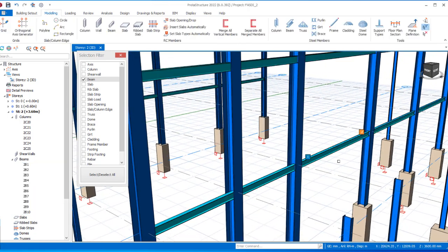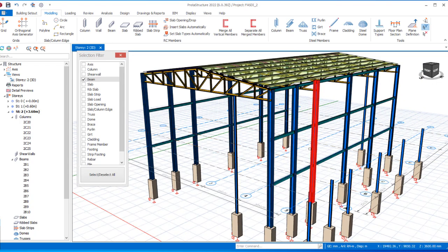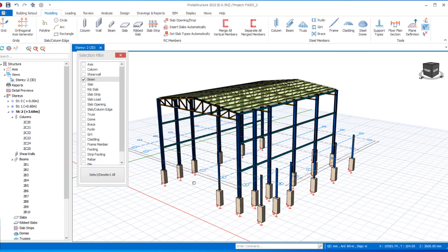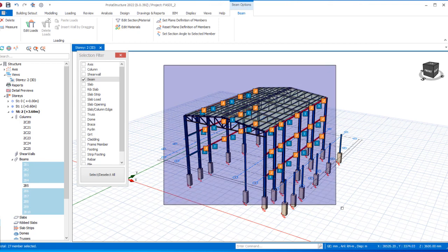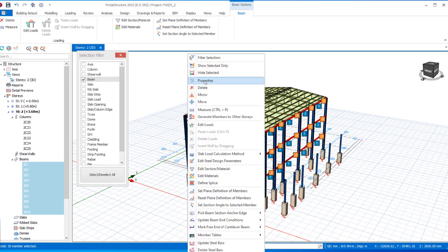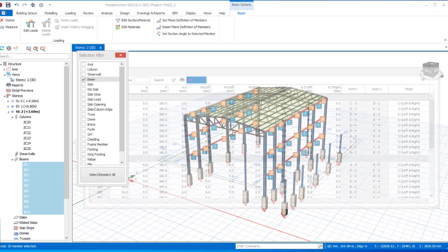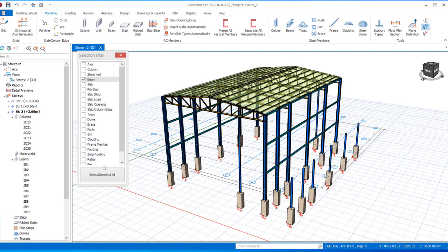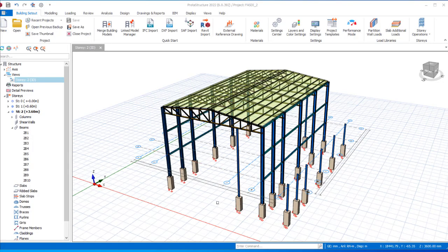This is good now. All right, so we can also proceed to checking if these sections has been released. Okay, so we have to select all of that again. Sorry, select all the structure. It is only beam that will be selected because it's been filtered over here. So you can also right click and click on its properties of the beam. So if you check over here, you can see both end has been pinned successfully. This is how it's supposed to be. All right, we close this. Okay, so now you have to make sure all of this is selected back like this before you close this dialog successfully. So we'll be stopping here for now.